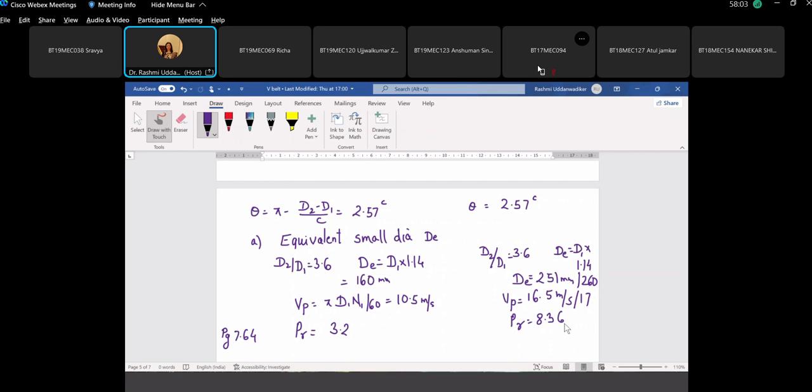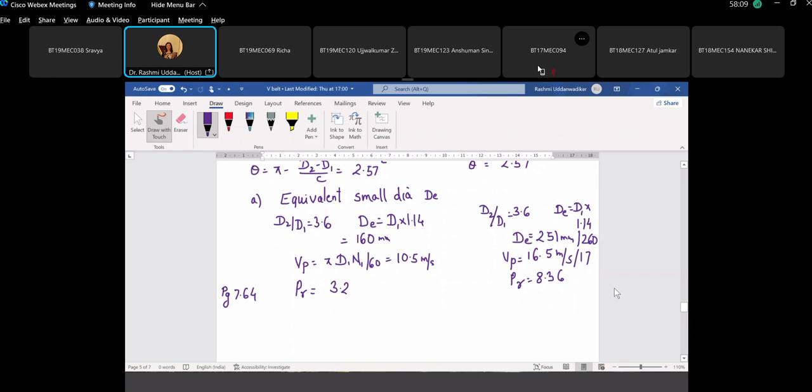Here we are simply trying to understand the design procedure. Our aim is not to get an exact answer, but to understand the procedure. If you want to get the exact value, you'll have to take an average from the data given. Is this part clear? For C cross section? Anshuman, you have given me the answer, which means it is clear to you. Okay, which means one belt with B cross section with this equivalent diameter can transmit 3.2 kilowatt of power, and if we take a C cross section, this can transmit 8.36 kilowatt of power. But this would again reduce with more correction factors.